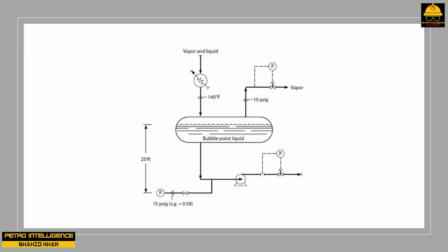But where does this large increase in kinetic energy come from? The answer is from the pressure, or feet of head, of the liquid itself. The conversion of the pump's suction pressure to velocity in the eye of the impeller is called the required net positive suction head, NPSH. As the flow control valve on the discharge of the pump shown in the picture is opened, the velocity of liquid in the eye of the impeller goes up. More of the pump's suction pressure, or feet of head, is converted to velocity, or kinetic energy.